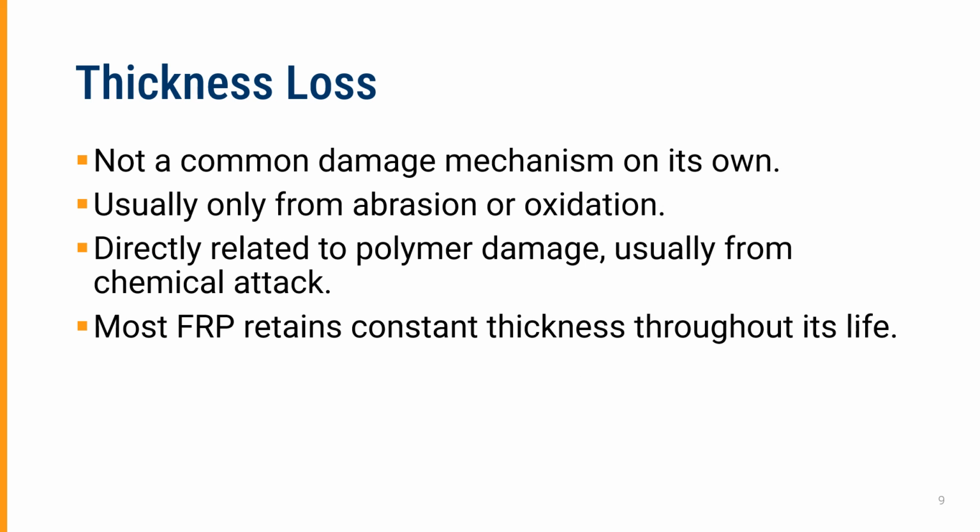Thickness loss is a huge, important consideration for steel and metal alloys. It is not nearly as important to FRP. It is not a common damage mechanism on its own. In fact, it usually only comes from abrasion or oxidation, or perhaps from weakening or damage to the polymer as a consequence of chemical attack. It's directly related to polymer damage, and it's usually from chemical attack.